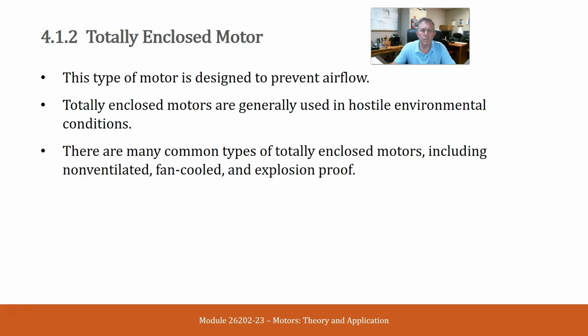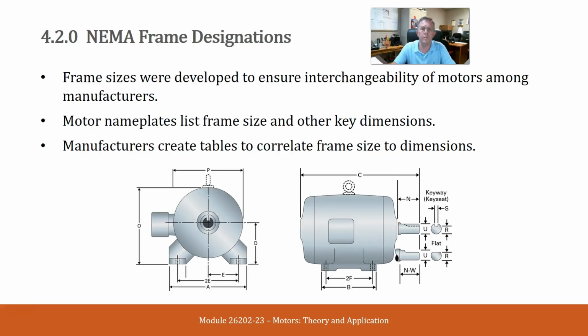Totally enclosed motor. This type of motor is designed to prevent airflow. Totally enclosed motors are generally used in hostile environmental conditions. There are many common types of totally enclosed motors, including non-ventilated, fan-cooled, and explosion-proof.